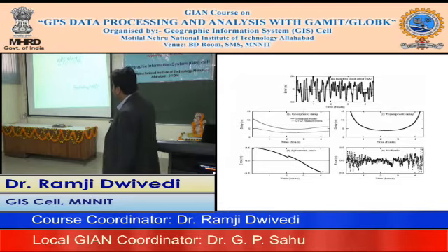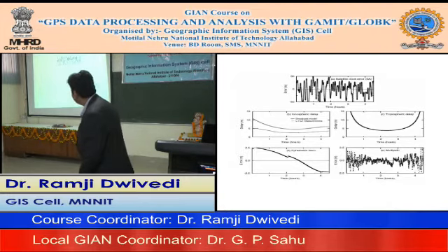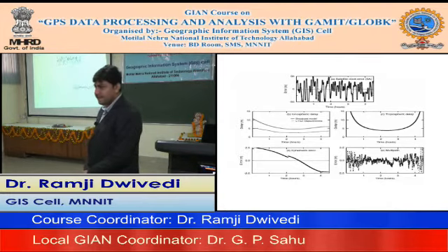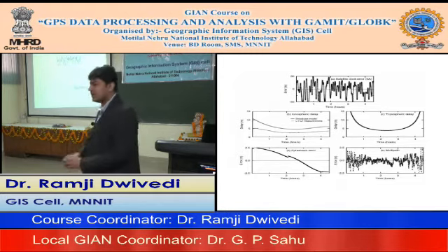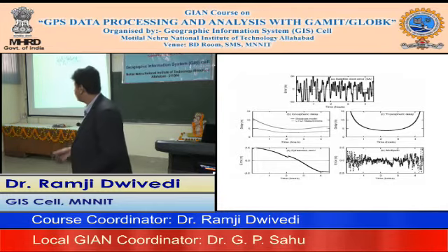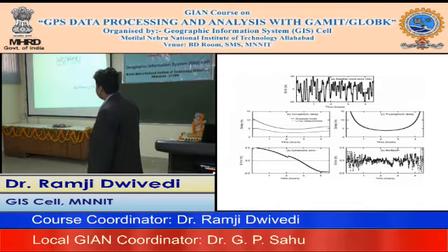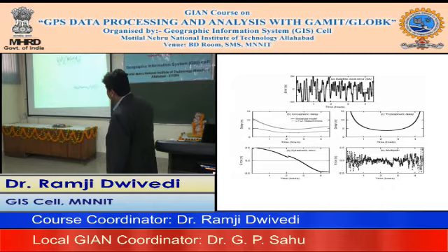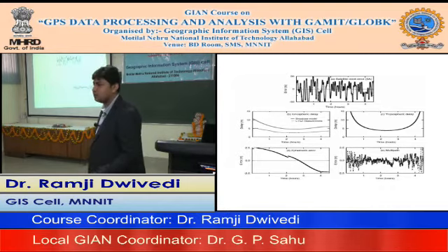And similarly to the ionospheric delay, you could relate the shift between the two delays, the below one being the estimation, with respect to the top one. Satellites also send certain parameters which take into account the atmospheric term, so when you are using the broadcast ephemeris data, you could use the Klobuchar model where these alpha and beta terms come up. The error estimated would be a little higher, but you could see that there is still a component. That's why we use the word reduced instead of removing.